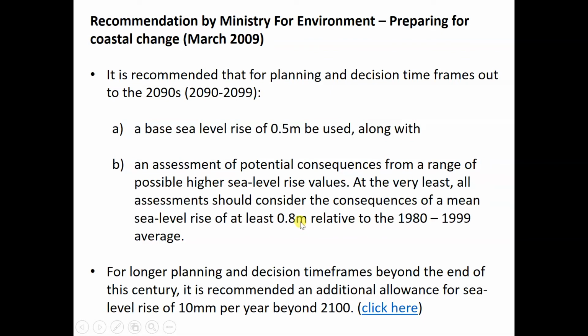But I think if you do projects around New Zealand, there will be some bylaws. There will be guidelines to see how much sea level rise you need to consider. For longer planning, beyond 2100, that is about 90 years, you need to allow 10 mm rise per year.